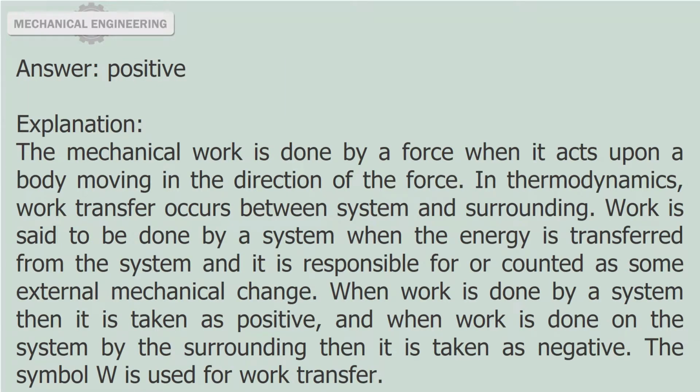Answer: positive. Explanation: the mechanical work is done by a force when it acts upon a body moving in the direction of the force. In thermodynamics, work transfer occurs between system and surrounding. Work is said to be done by a system when the energy is transferred from the system and it is responsible for or counted as some external mechanical change. When work is done by a system, it is taken as positive, and when work is done on the system by the surrounding, it is taken as negative. The symbol W is used for work transfer.